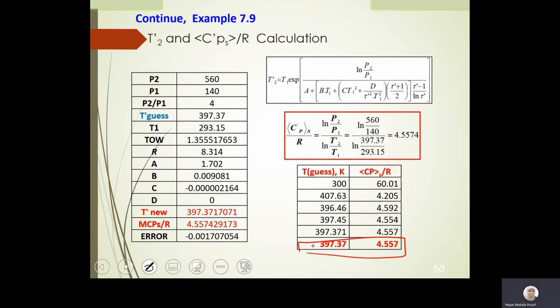Now I did that derivation and I put delta H dash over delta H for compressor. We cancelled the CP from both sides, and that's why you get this equation. So same thing here. I'm just using the equation after being derived, and no need to put the CP, and we got the T2 as 432.11. In other words, if I assume constant heat capacity, I'm going to get 432 degrees C, while here it was 428.